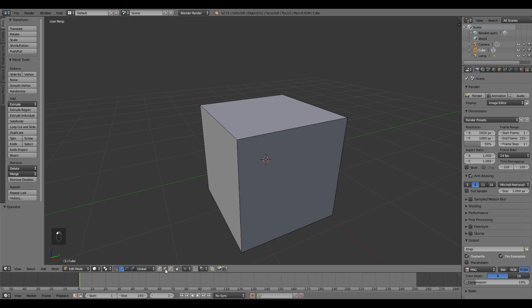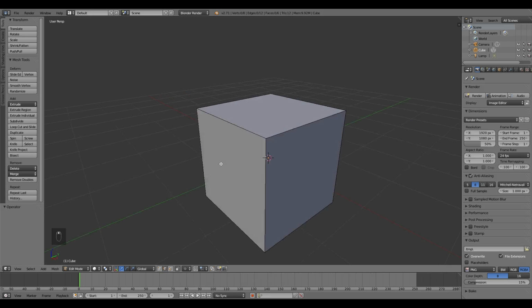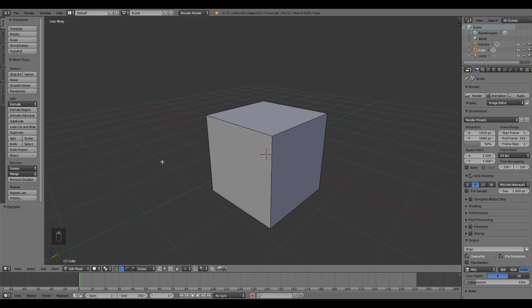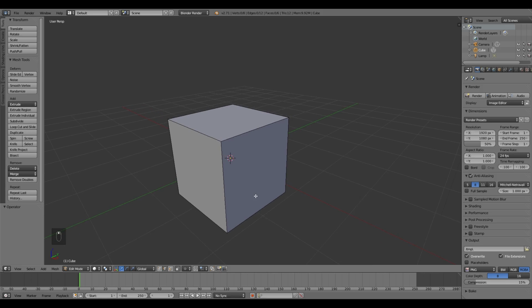Click that. Or for those of you that would prefer to know the shortcut, and personally it's a better way to go about things, if you hold Control down and then tap Tab, you get this option pop up. Lets me select vertex, edge, or face. We've already looked at vertex, we want to select edge. So left click down and we have edge selected.